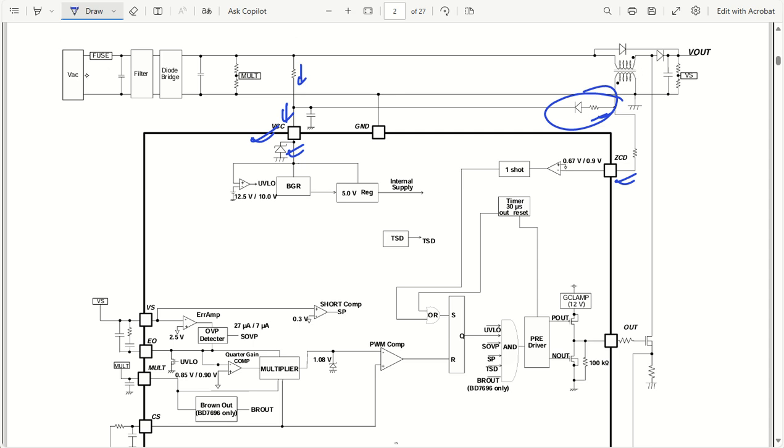As I told you already in the beginning itself, we have the AC source, we have fuse protection, then MOV. I mean, MOVs you can also put if you want. That is also always recommended. Then we have all these X capacitors and then filters. Filters is nothing but CMC chokes or something like that, that is common mode choke. Then we have X capacitor. No, this is not an X capacitor. This is the bridge after rectified voltage. This is the bulk capacitor that you can consider. We can also have some other capacitor that we'll see in detail, like how to design this particular phase.